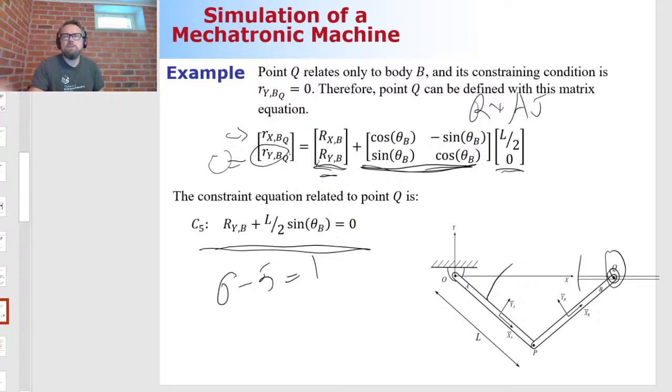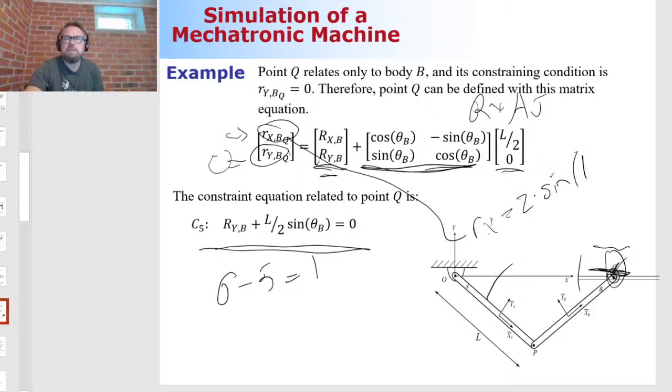Okay, so we just concluded that this system has 1 degree of freedom. What if I eliminate this 1 degree of freedom, by saying that this primitive joint here cannot move freely along the global x-axis, but instead this is a motion that is predefined? So this would be something like saying that this Rx has to be equal to, say, 2 multiplied by sine theta multiplied by 2.